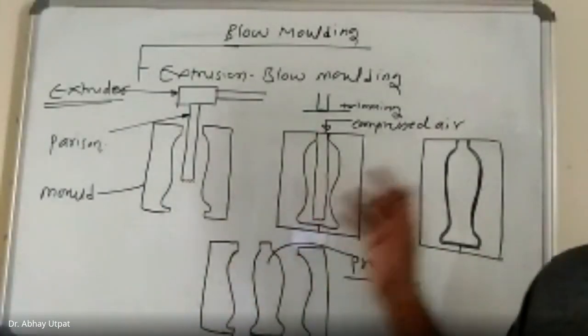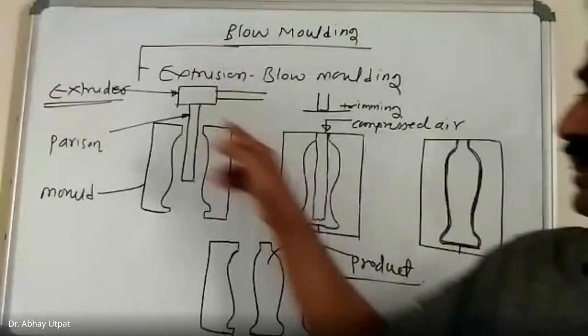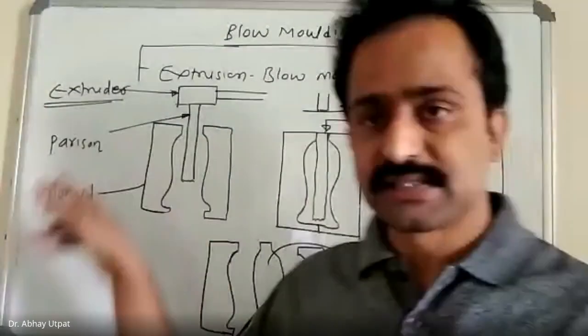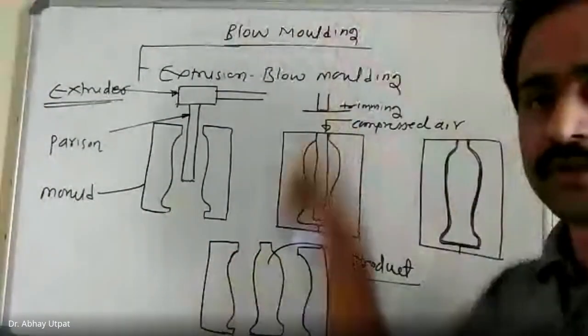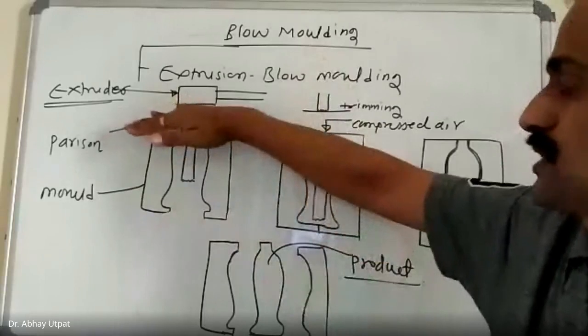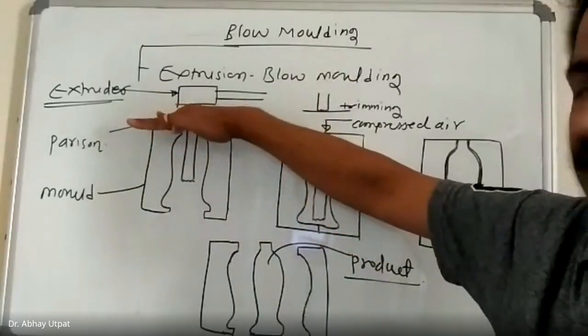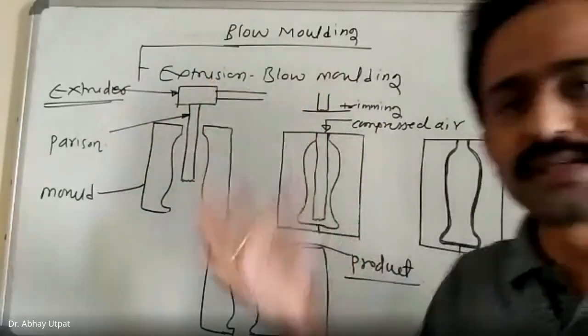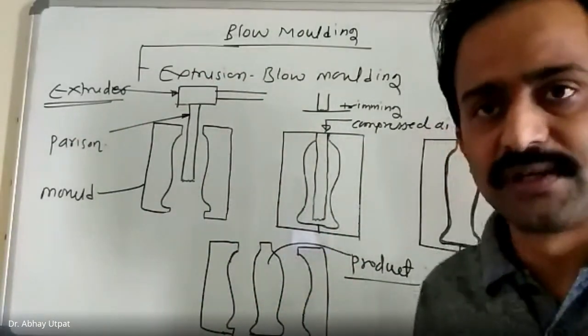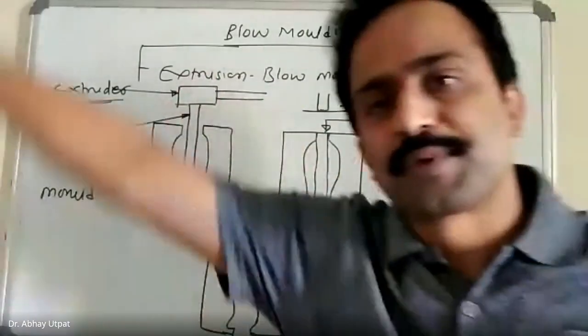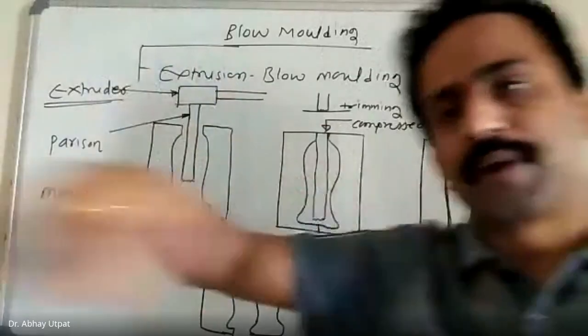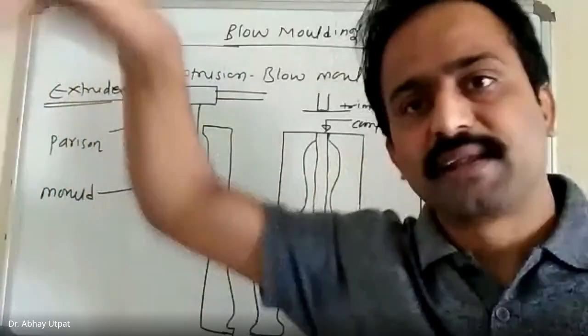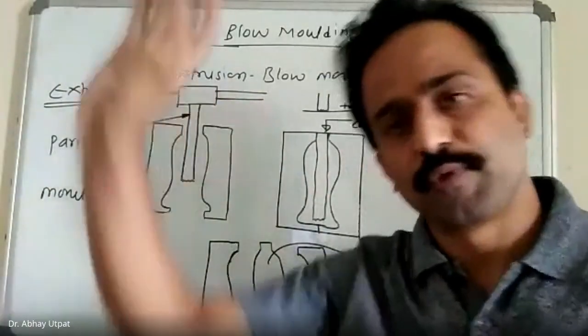Why is it called extrusion blow molding? Because the raw material parison comes directly through the extruder. So this is a continuous process. If you look at the figure below, the upper process is only termed the extrusion molding process, where a long pipe is produced. At that time, that long pipe was our final product, and then it may be wound for dispatching.